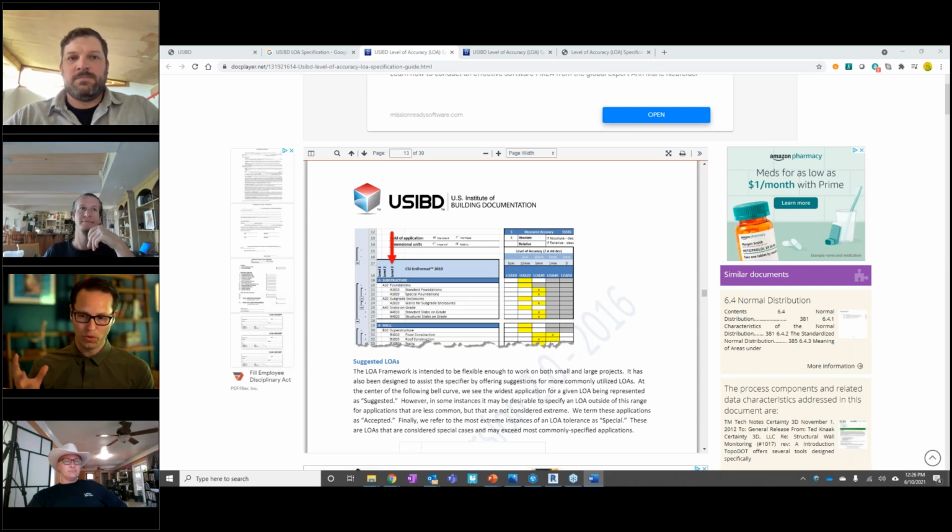So after that discussion, once you have everything written down, you can start working on your model setup. But the first step, even having the discussion with the client, is setting up your levels, grid and orientation of the project. One mistake that I've seen a lot, not only in the building documentation industry but also in design and construction, is bringing links in center to center, origin to origin, which I think is a mistake when you can take advantage of the shared coordinates.